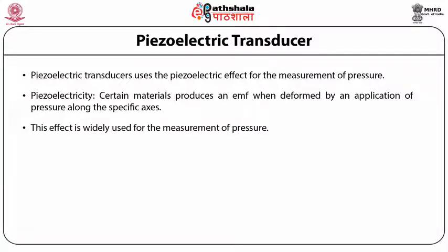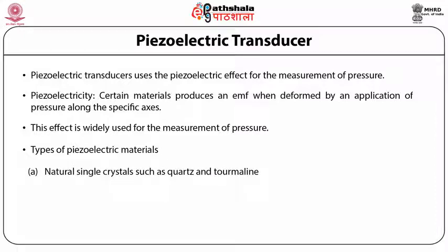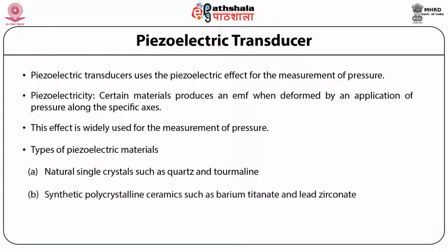A piezoelectric crystal should have a charge asymmetry, that is, the center of the positive charge of the crystal does not coincide with the center of its negative charge. There are two types of piezoelectric materials. First is natural single crystal such as quartz and tourmaline. Second is synthetic polycrystalline ceramic such as barium titanate and lead zirconate.